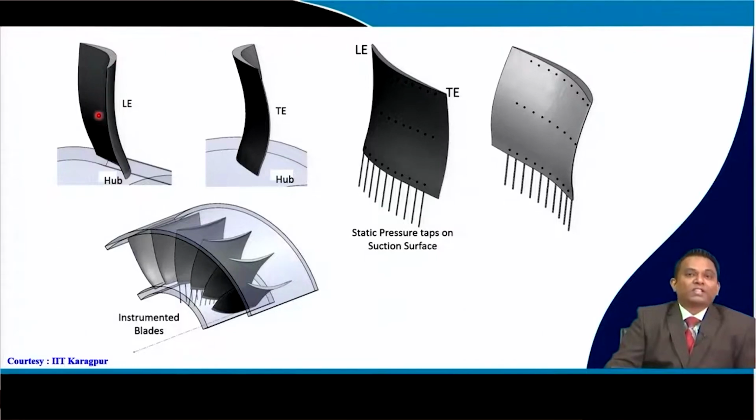If this is a three-dimensional blade, and we want to analyze what is happening with the flow physics, we need to go for testing, and for that testing I cannot go with the linear cascade tunnel. I literally need to go with the annular cascade tunnel. When we go with the annular cascade tunnel, we have discussed that based on power requirement and dimensions, we have a whole lot of limitations.